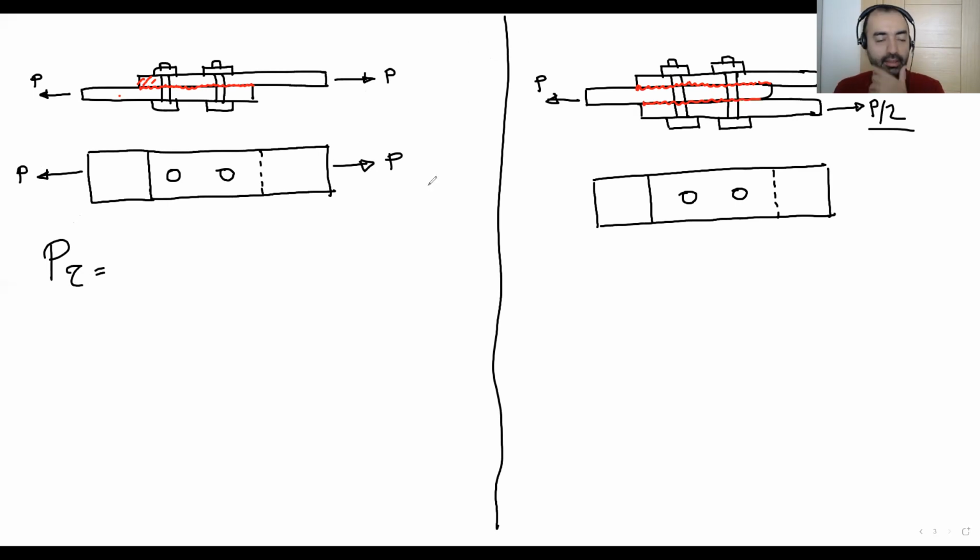Okay, I'm going to explain that later on. For one bolt shear capacity, the force is always area times stress. For one bolt, we have the sectional area, which is circular, times the allowable shear stress of that bolt. At the end, it gives us the one bolt shear capacity.